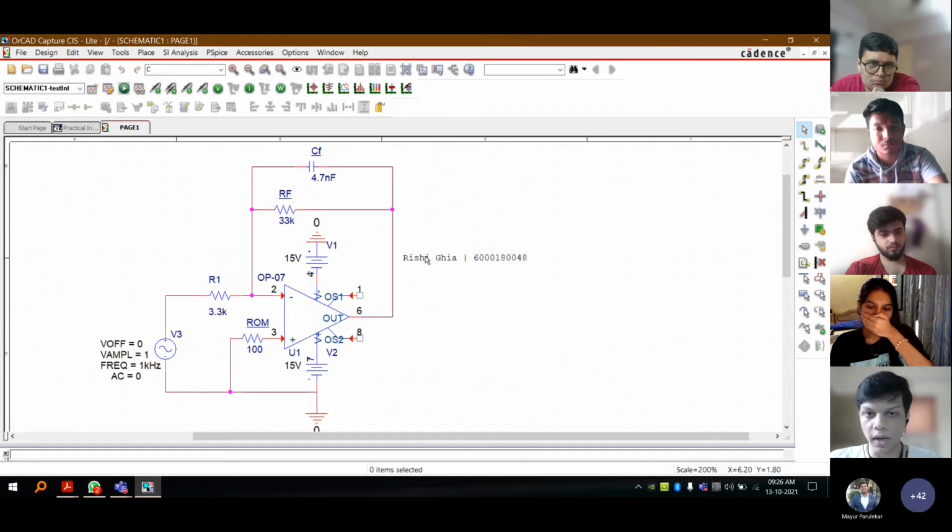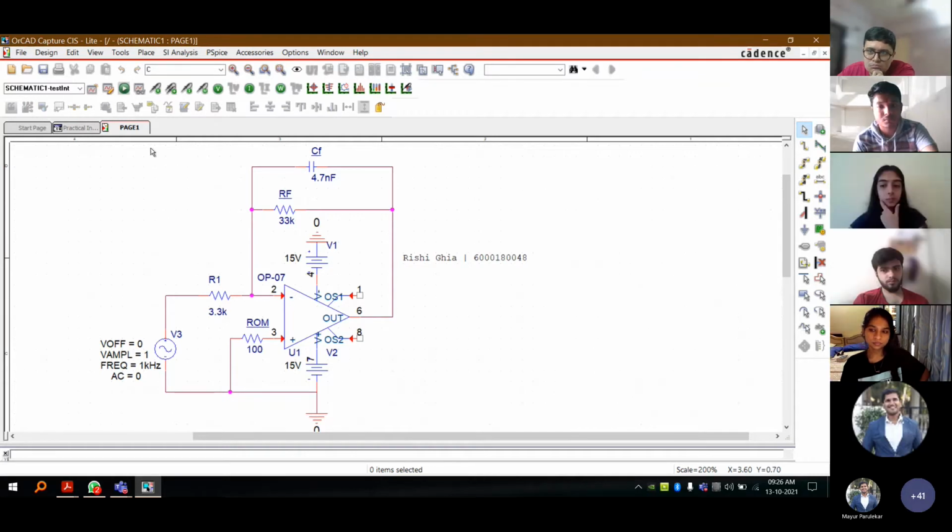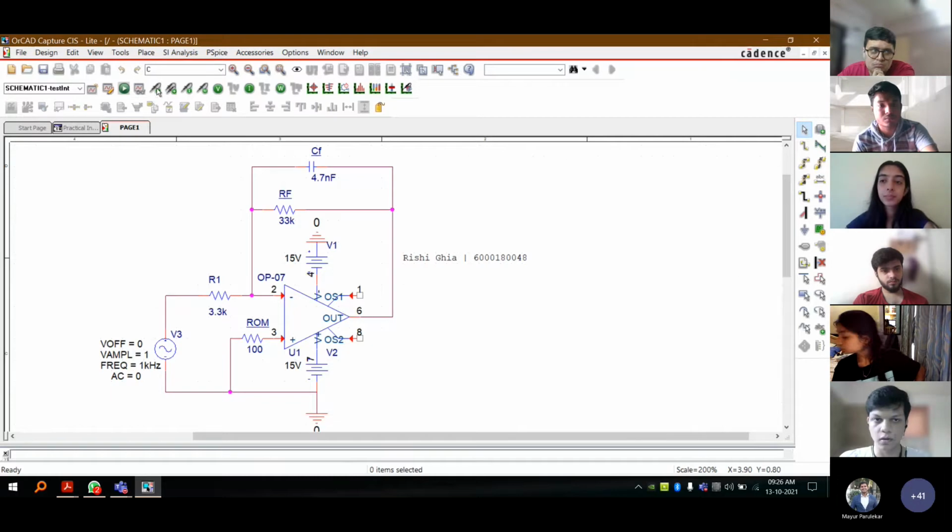All right. So in OrCAD, what you do is you give your terminals, like the terminals to check voltages, before you do the simulation. So I can just click this V button here with the terminal. I'm blanking on what it's called. I can just place one right here at the input. Again, you can rotate this as much as you want. I can place one here.